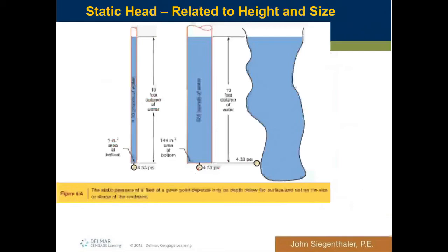Shape doesn't really matter either. So static head is really related to the height, and strictly the height. So let's take a look at this. Now in my example here, I've got a skinny little tube, and it's showing the same 4.33 psi.